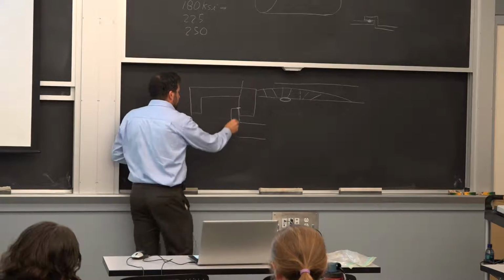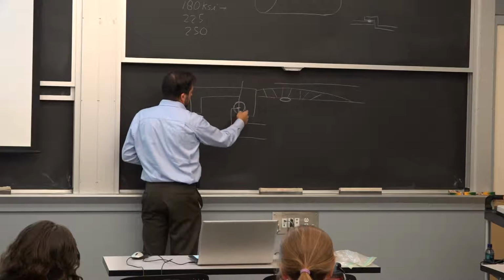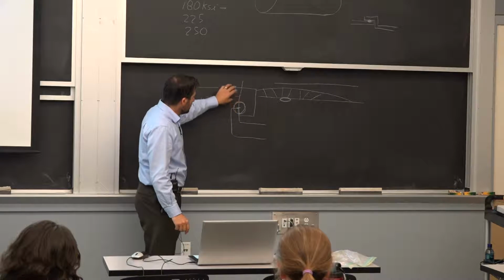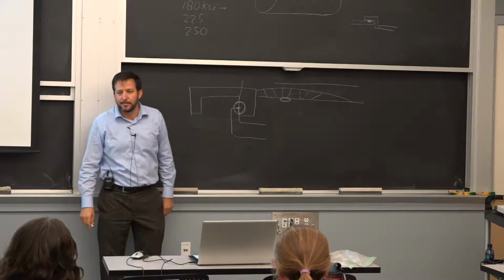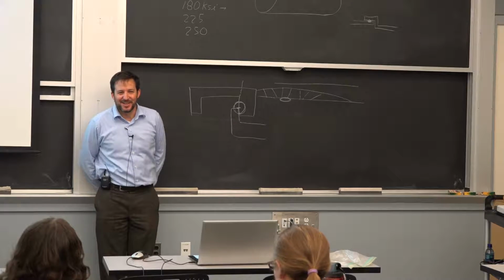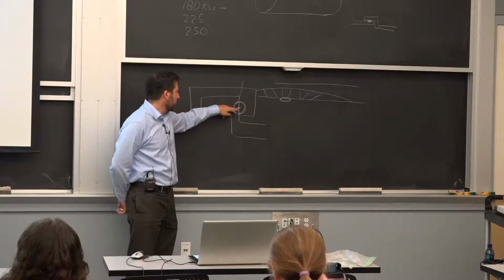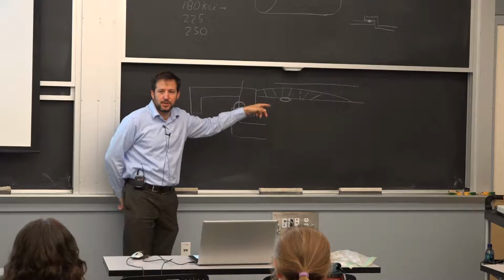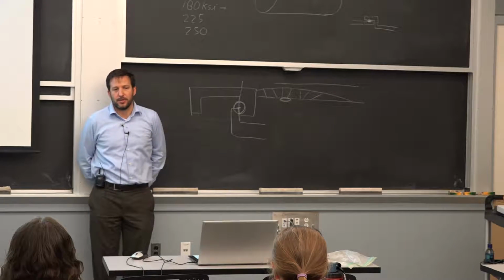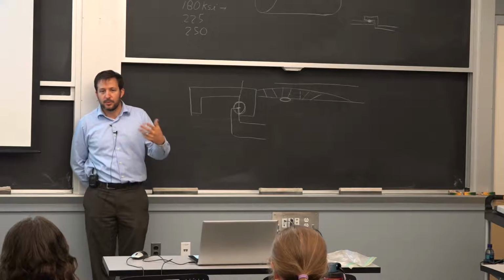So from this indication of contact between the end of the pipe and the clamp, I essentially determined that this clamp was not fully engaged into the pipe, and that's why it broke. It looks simple, but you have to be looking exactly. This mark was the furthest from the corner here at the position where it broke, and then it was going to a higher engagement at the other location. So the clamp was not sitting square.